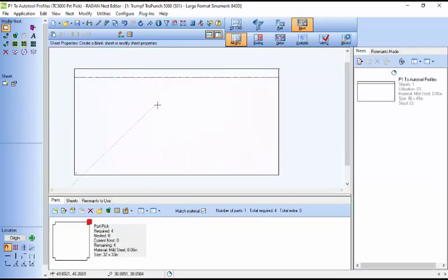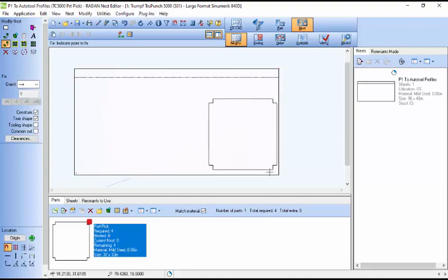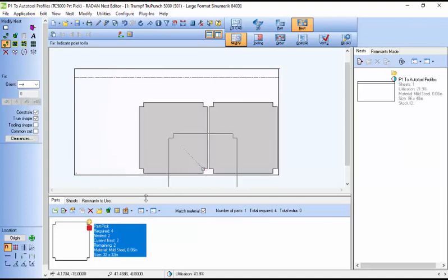So typically on your Trumpf machine, your clamps are up on this edge here, and your Sheetmaster comes in this way, and the programmer or the machine operator is standing off to the side. Okay, so now I'm just going to drag this part up here and drop it down. Let's put it in the top corner, put another one there, right, and then I'll just cancel that operation. So there are my parts, they're all ready to go, they're already tooled.